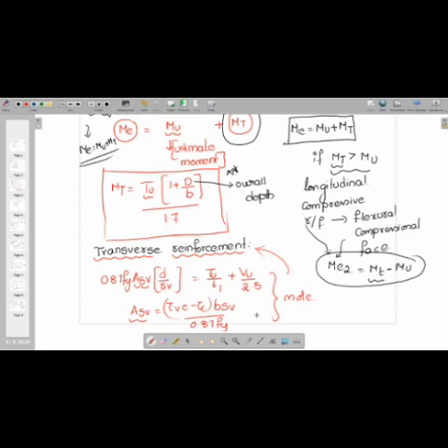Then you will see which is more of the two, and take that one. Actually, there are two reinforcements. One, you provide the main longitudinal, and the other you provide the transverse. So in transverse we have two formulas for Asv. Whichever is more, take that. Have you written, sir?